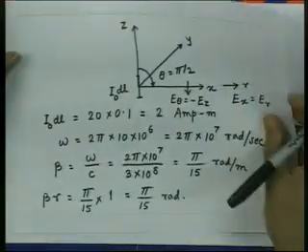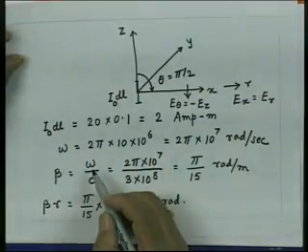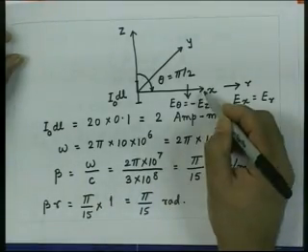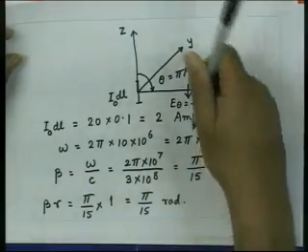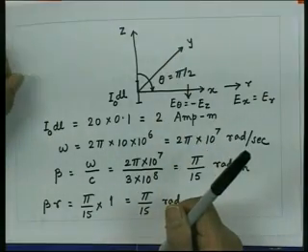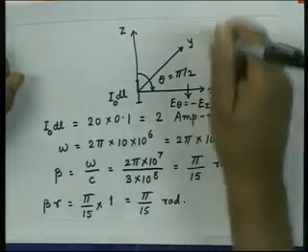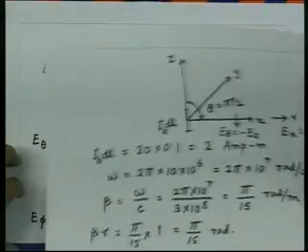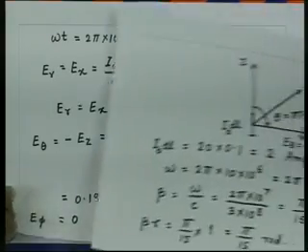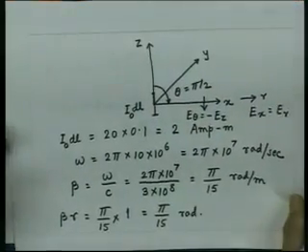So, in this case, if you move along the x axis, then the r component is 0, the theta component, which is same as the minus z component, and the phi component also is 0, which will be perpendicular to the plane of the paper. So, by using the expression which we have derived, now we can find out the total field at a distance and at some instant of time from the Hertz dipole. Let us take next problem.